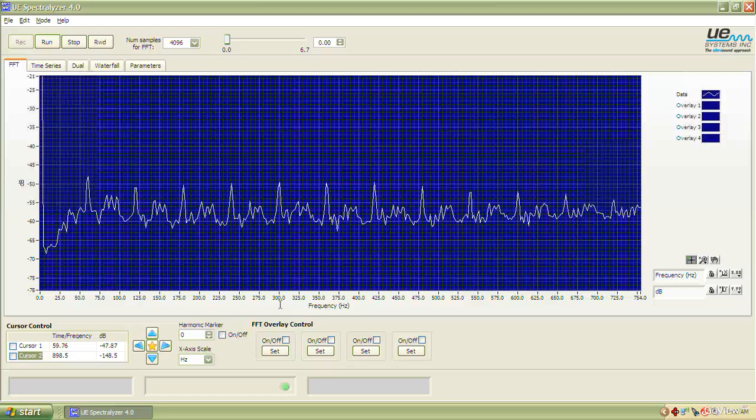On the x-axis of an FFT, we're looking at frequency. In sound we generally deal with hertz, cycles per second. So we're looking at that in hertz. You do have the capability of changing that scale to cycles per minute. Alright, we'll leave it in hertz, as that's normally the way we do it, but you can use cycles per minute if that's the way you like to look at it. Okay, looking at the same thing, just different terminology there. Now, we see corona here.